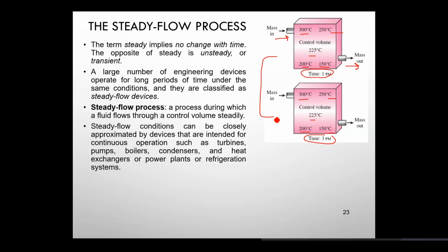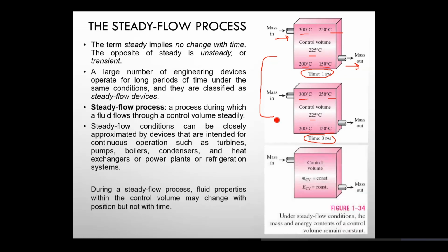Clear? This is one of those assumptions that you'll use with open systems when you're analyzing them that makes your analysis easy. However, the analysis is quite correct. Clear? And the bottom line of this steady state assumption is this: within the control volume, if it is working under steady state conditions, your mass within the control volume remains constant, and your energy within the control volume remains constant. So the mass remains the same, and the energy within the control volume remains the same in steady state conditions. Clear? Any doubts with this? All right.